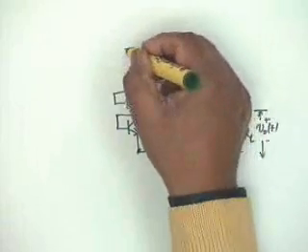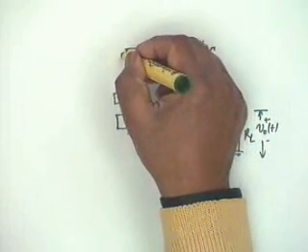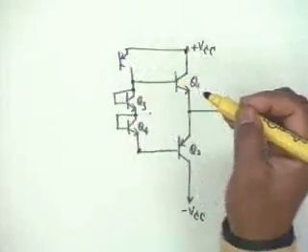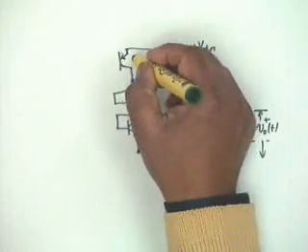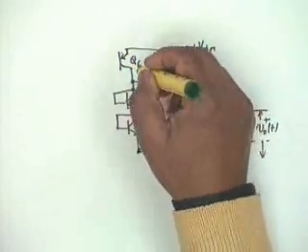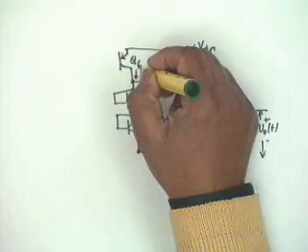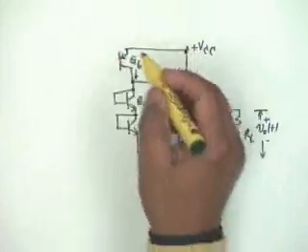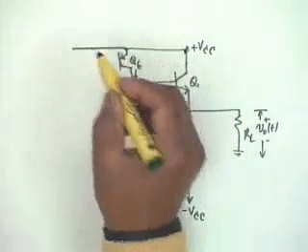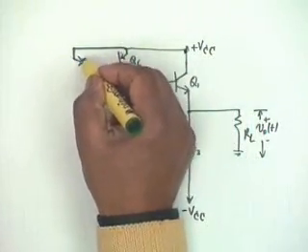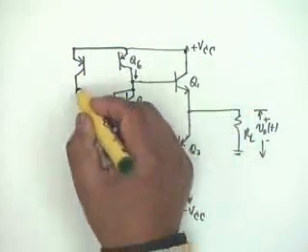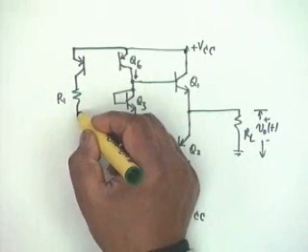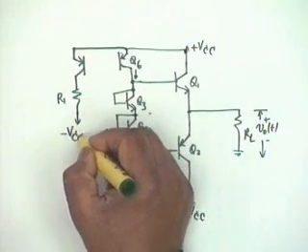So what we do is from here, from plus VCC, we take a transistor. Now obviously the current mirror shall have to be PNP. Okay. So this is what comes here. This is Q6 and this current is, let's say, oh, I'll do it later. And the other one, the reference transistor, is this one. This is also a PNP and we require a small resistance here, R1, and this can go to minus VCC.